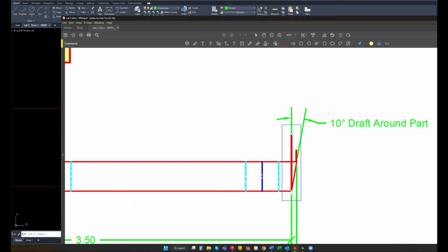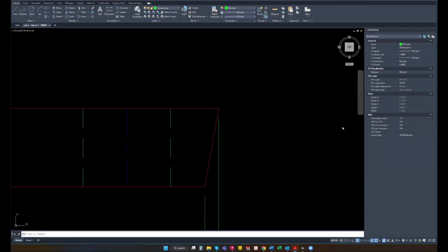And then obviously this point here, just like that. So we have this line to snap to, but we don't actually have anything here to dimension off of right now. So what we're going to do is I'm going to use my construction layer, L, enter for your line tool. And I'm just going to draw us a line straight up, just like that.